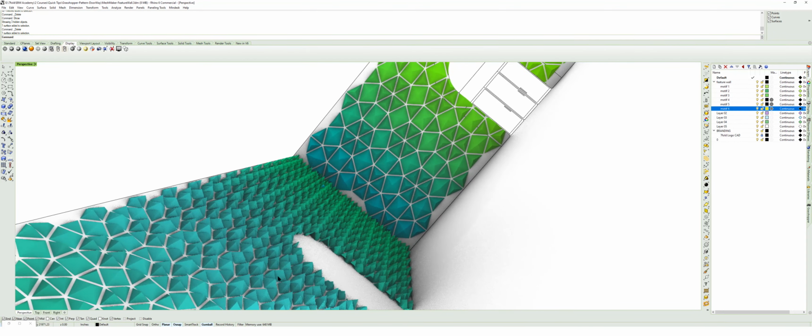I'm going to hide some of this stuff so I can see it more easily. And then I'm also going to go up to edit and go down to mesh explode. Plugging in my M to here, it's going to help me see. And then I want to do mesh edges, typing in mesh edges, plugging the A into the M. It's going to give me all of my edges.